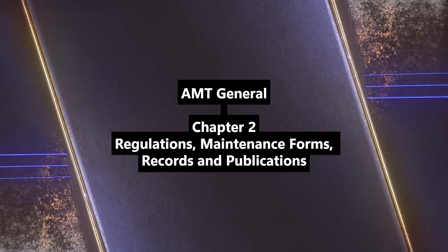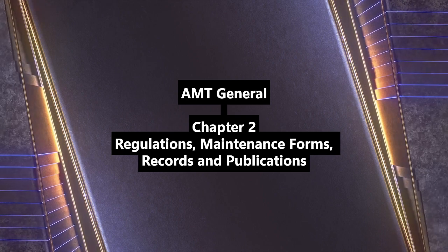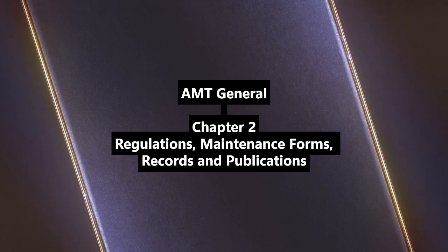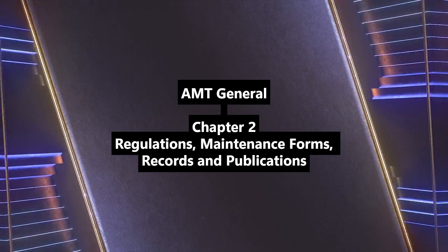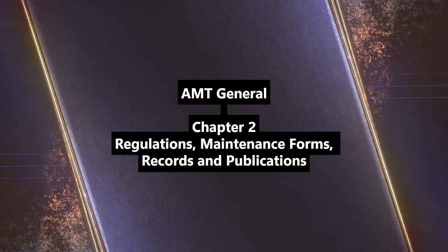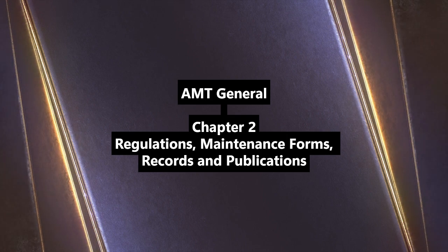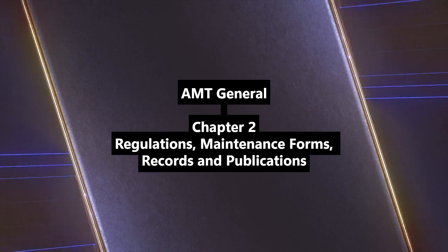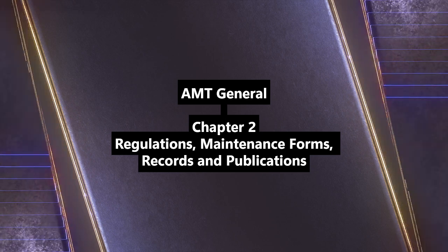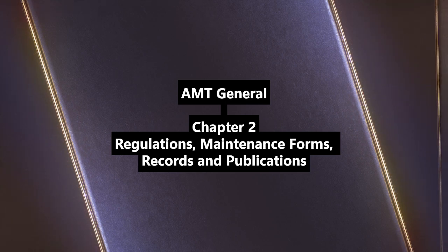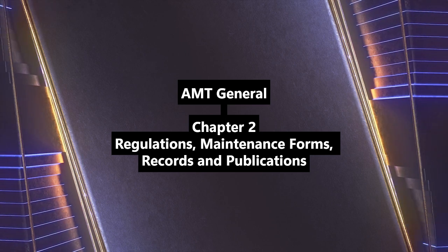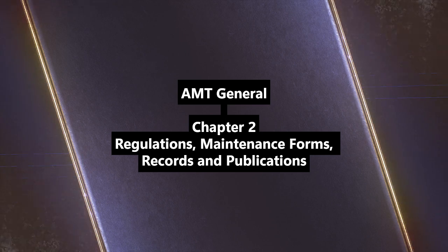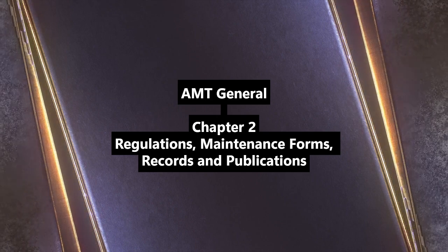Appendix F. ATC transponder test. The 413 test. Also every 24 months, per 91.413, and after installation or maintenance, test the whole system: the static system, per Appendix E, and the transponder itself. Specific tests like frequency, sensitivity, power output, and mode S require log entries. And who can do this one? The manufacturer, a rated repair station, or a Part 121 or 135 operator with it in their continuous airworthiness program.